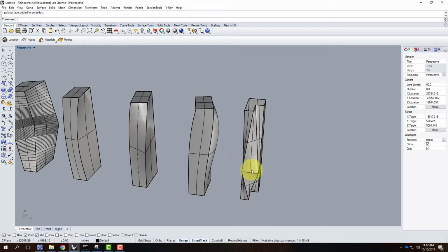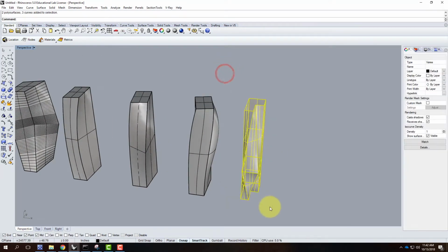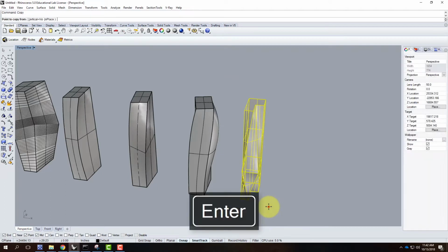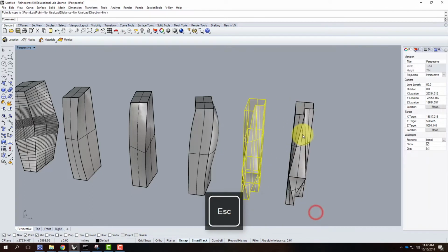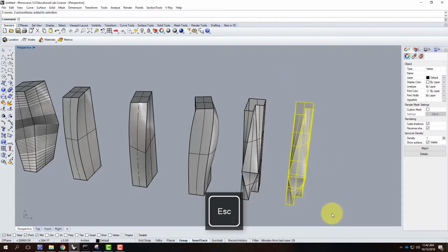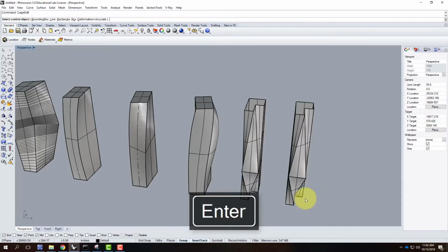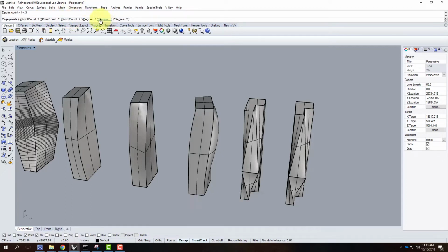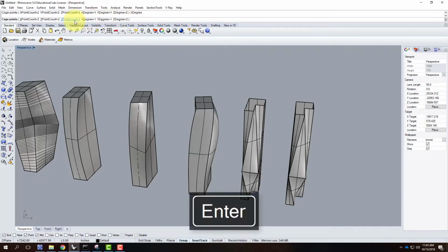Once I have this, I could also take this particular piece and I could perform a cage edit of this. So I could take this and go to cage edit, bounding box, world, go back down to 2, 2, and I'll leave that at 3 for right now. My degrees, yeah, that's all fine. Hit enter, global. There are my points.